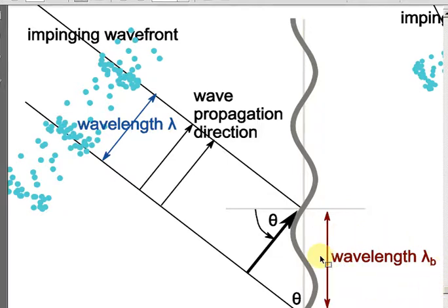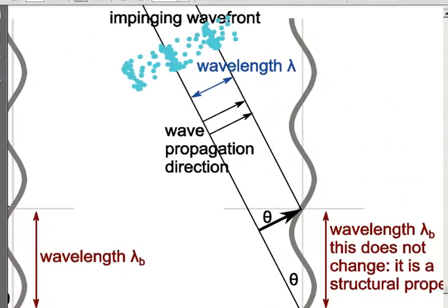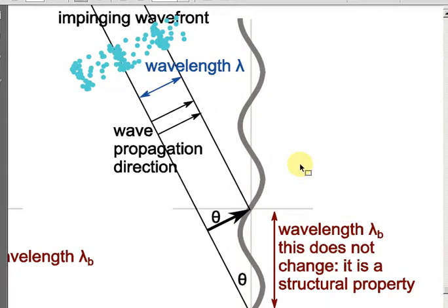As such, we have that special case that we described. So when the angle gets smaller, figure 66 in your notes shows that this would correspond to a different acoustic wavelength projected upon the panel. And keeping in mind that the bending wavelength does not change, because it is inherent to the structure itself.